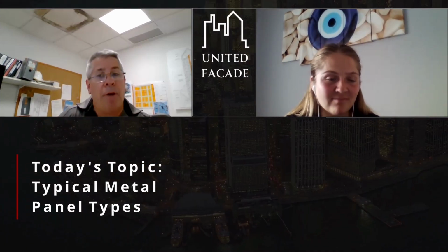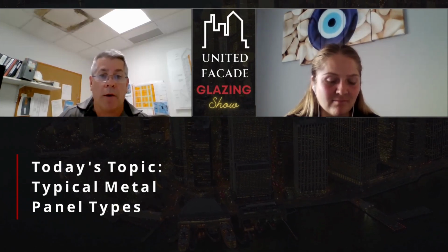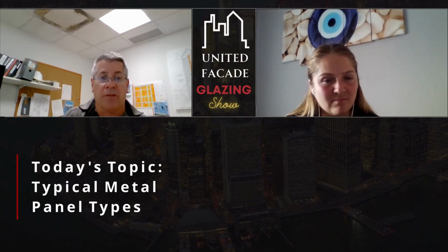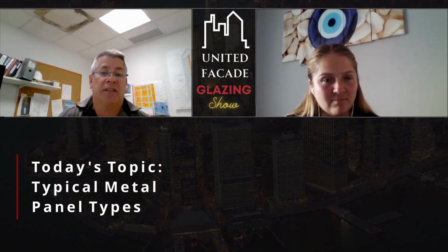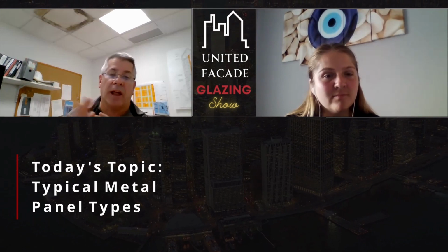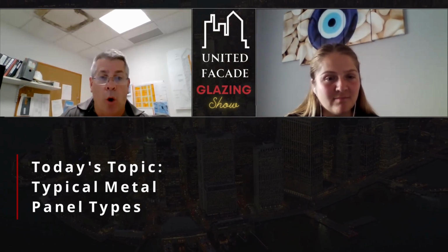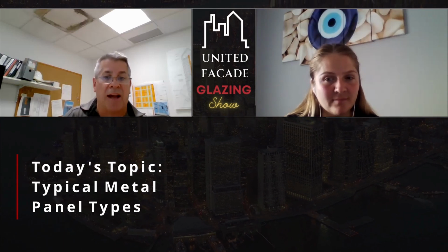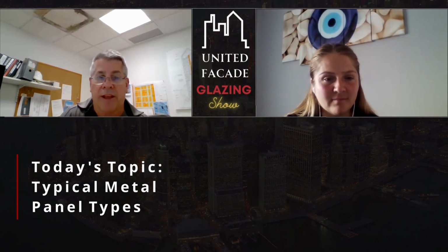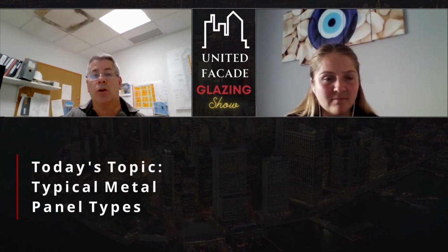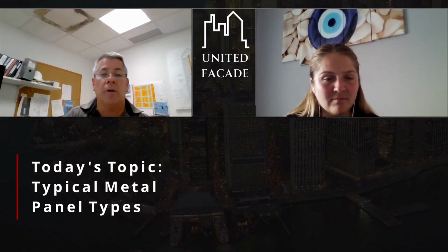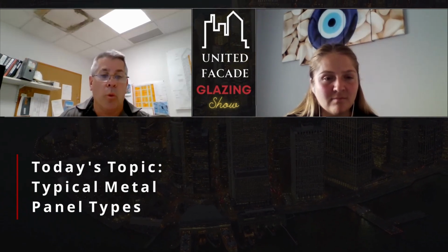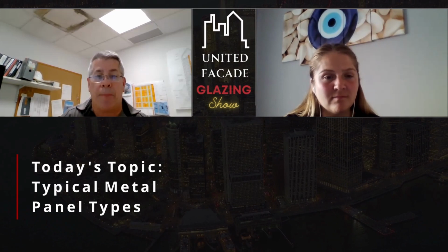I've seen it just be plate panels before, but remember, the higher up you go, you're getting wind loads. If you have a big flat panel up there, it's almost going to act as a sail, or you get a lot of pressure on that. So by putting holes or perforations, whether circles, ovals, or slots, whatever the architect wants his design to be, that's going to allow the wind to pass right through it. So it's not going to deform or deflect or take wind loads against it. It's going to allow the wind to pass through it.